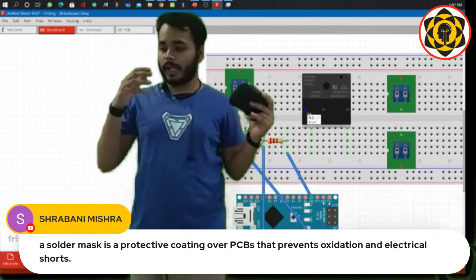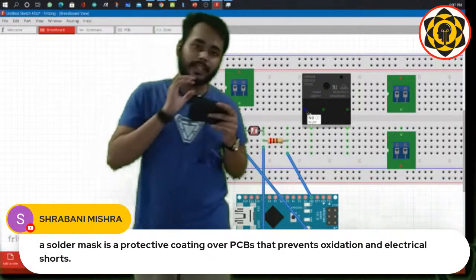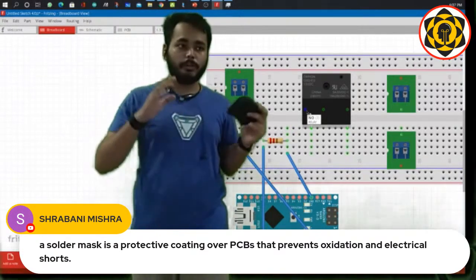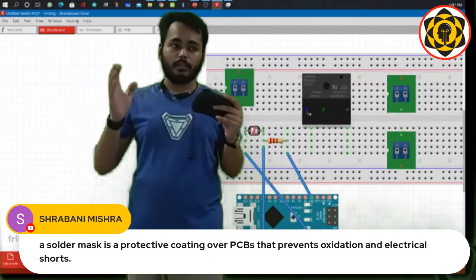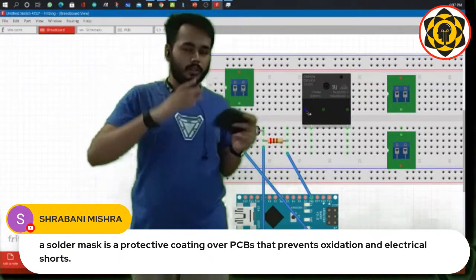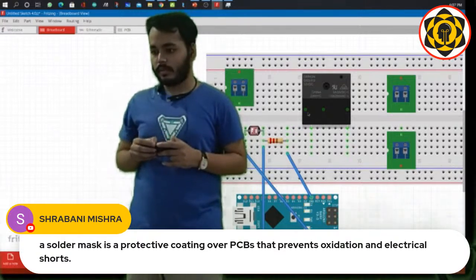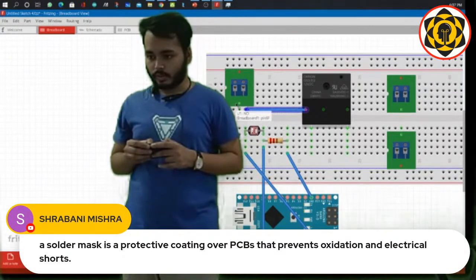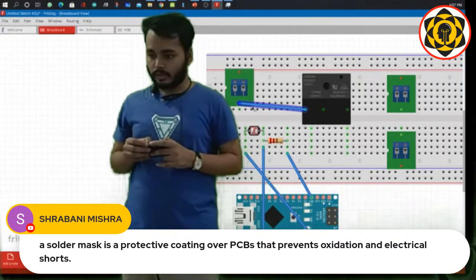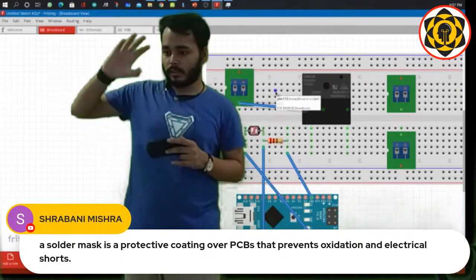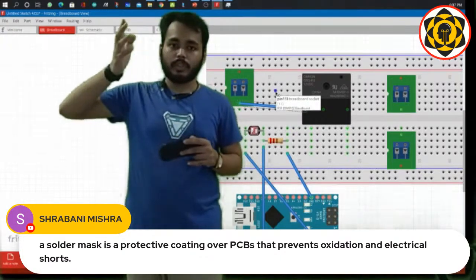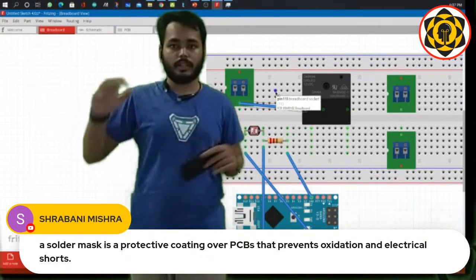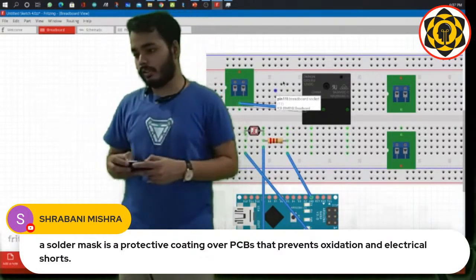So we need the bulb to glow when we send a signal to that thing. We will be using normally open, because normally open means normally it's off. When we turn the power on, it will turn on. So we're going to use this N open and connect it to one of these. Now we don't need to worry about polarity here, because on the relay side we are going to be using AC voltage, right? AC voltage does not really have any polarity. It's always alternating. So we don't need to worry about polarity.